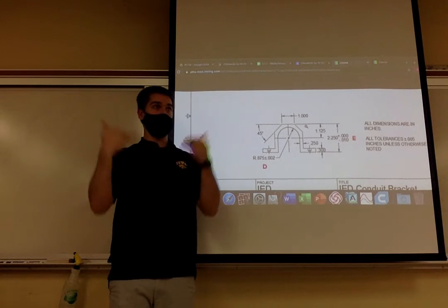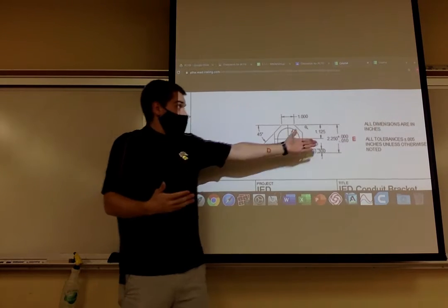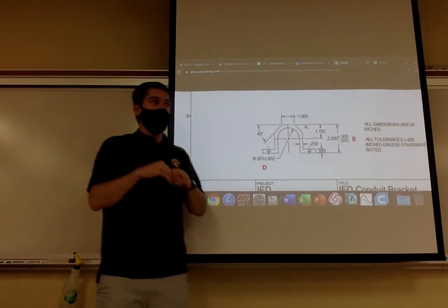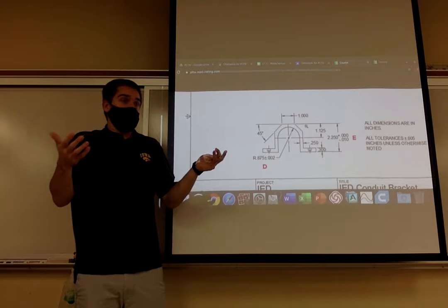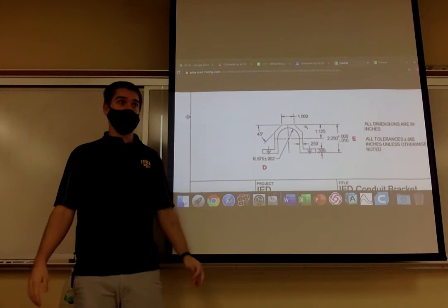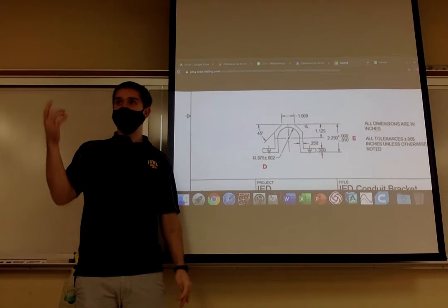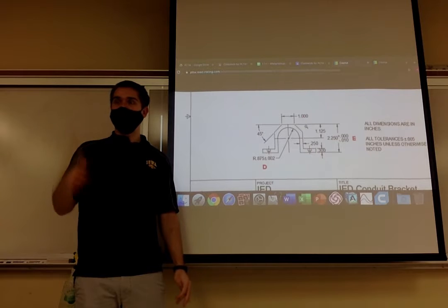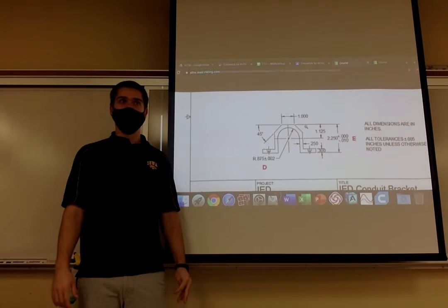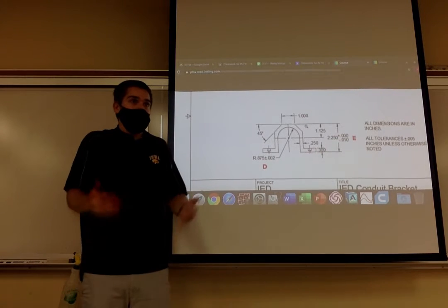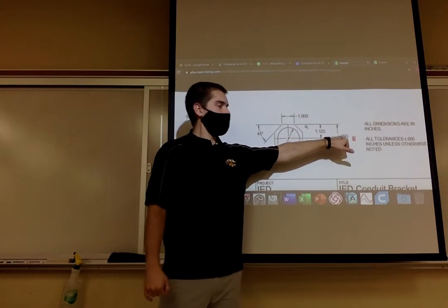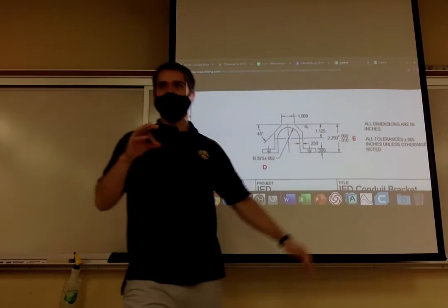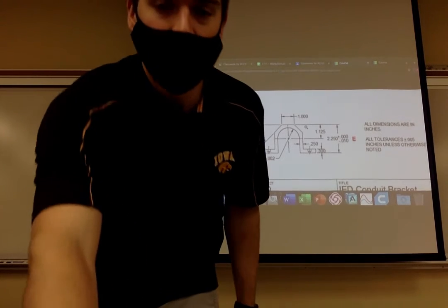You can let them make the pin smaller because it'll still fit. But if you gave them room for error on the upper side, it might be 0.55 inches. Well, would a 0.55 inch pin fit in a 0.5 inch hole? No. It completely fails. So, Kyle, that's a great example. This is times when you would need to go out of your way to specify certain dimensions.